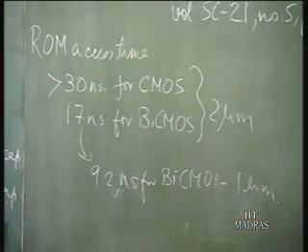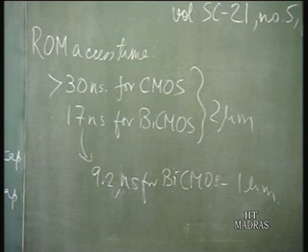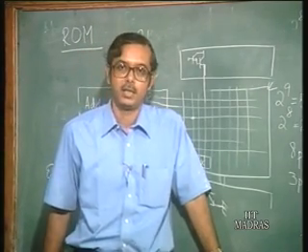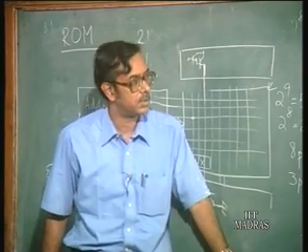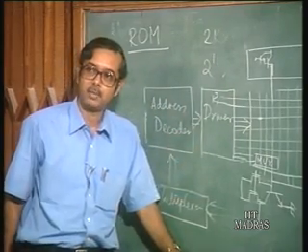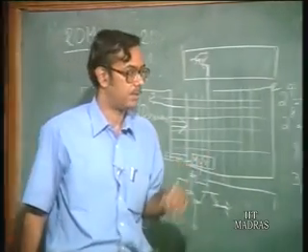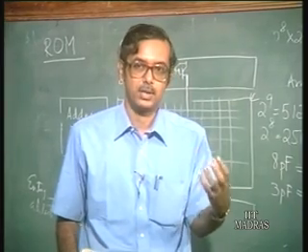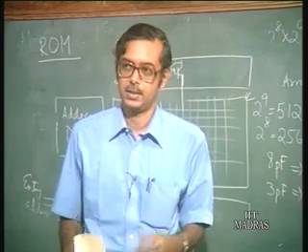So, you see that the comparison is with CMOS, and with judicious use of bipolar transistors, one can actually reduce the delays tremendously. In fact, the next topic which we will take up for the next few classes is memories. We shall also see the advantages of using BiCMOS compared to CMOS. The different memories give an example that bipolar transistors are very much useful in reducing the delays in memories. BiCMOS, where you use bipolar transistors judiciously to improve performance, is basically to reduce the delays or improve the speed.